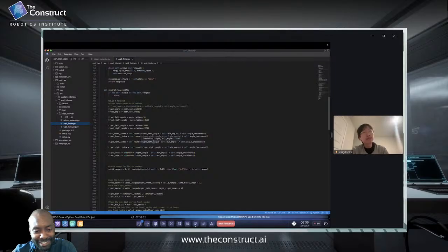That's what I did, and you want to make sure that for actions and servers, you want to run them concurrently. But I mean, you want to separate the data copies they're working on to reduce the offsets, because you might use different values for actions if you are using all of them in the same callback groups. If you don't separate them, it might get mixed up.